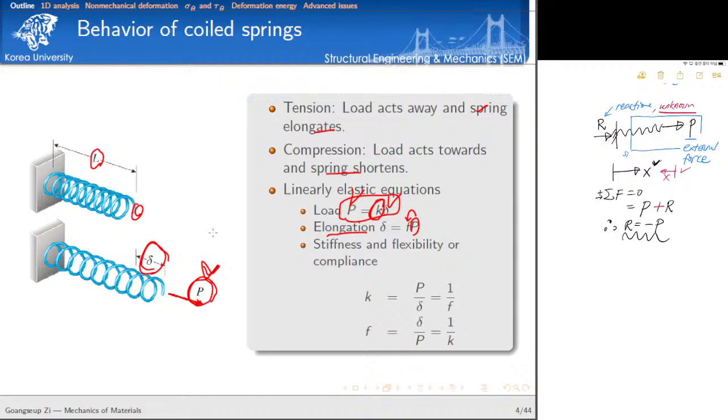Alright, so omega 1. So if you do that, to satisfy the force equilibrium condition, if you consider only this, this is omega 1. If there is no internal force, we cannot satisfy the force equilibrium condition. That's why we can conclude that there should be internal force.